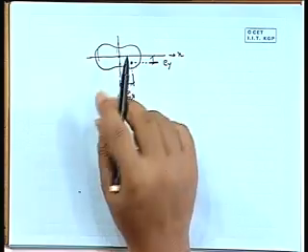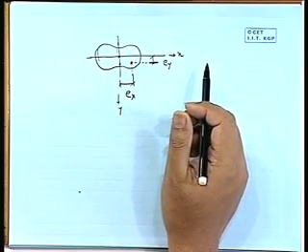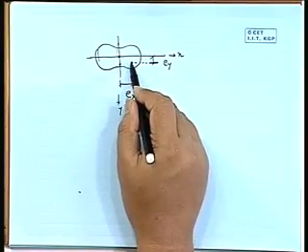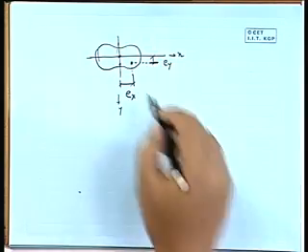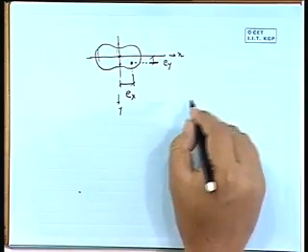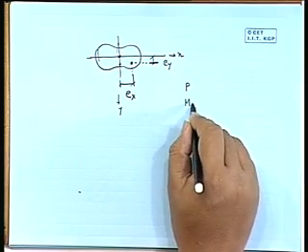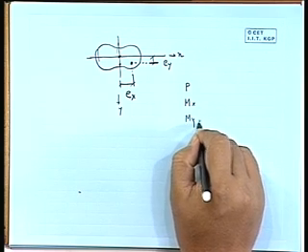So, this load we can shift here. So, it will come here with a moment P into Ex about y axis. Now, next step, if you shift that load, there will be a moment along x axis P into Ey, right. So, what will be happening? If we shift here, ultimately at the centroid we will get P and there will be a moment about x and there will be a moment about y, right.